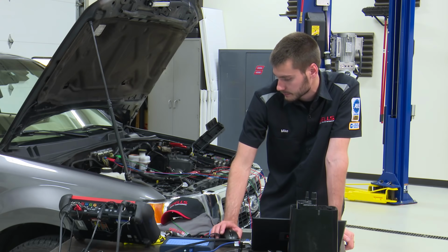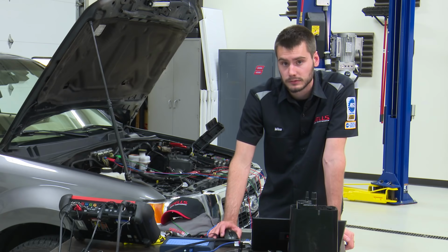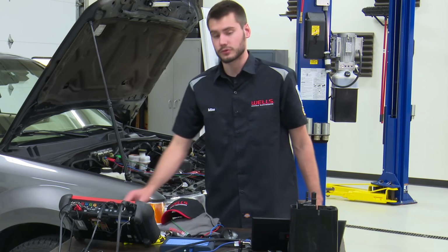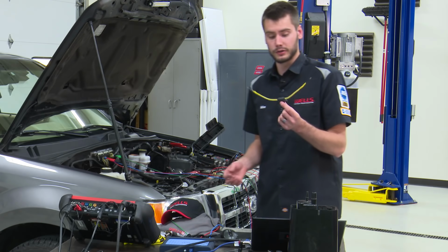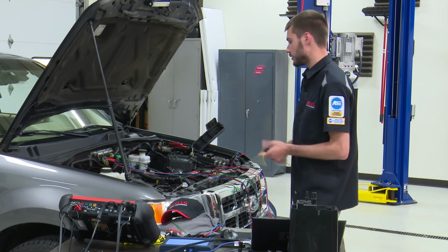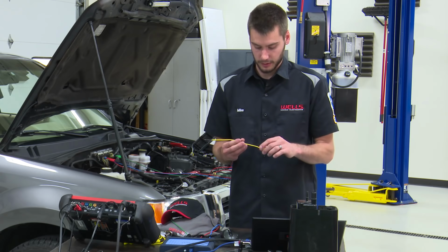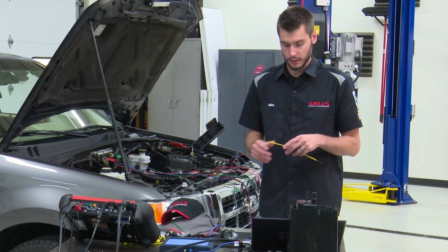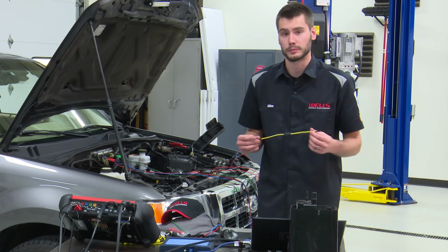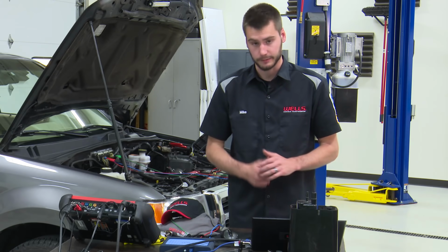And yeah, as you can see, I don't have a power probe anywhere. I don't use them. It's a personal choice. I use something like this. If I want to supply power or ground, I'll use a fuse jumper wire on there, just because it's the way I was taught and the way I do it. You guys probably have or used power probes. More power to you. I've seen other guys wreck things with power probes, so just keep that in mind when circuit checking, okay?